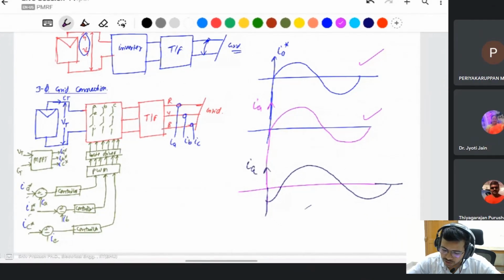If suppose this is the same signal, there is some tracking, and maybe you can track this system. But in that case, what happened? It starts from here, but the phase is shifted. Then how do you control this one? This is the difficulty in controlling the AC system. They use a tracking controller in this system, but there are many types of problems in a tracking controller, like low bandwidth to control the signal.